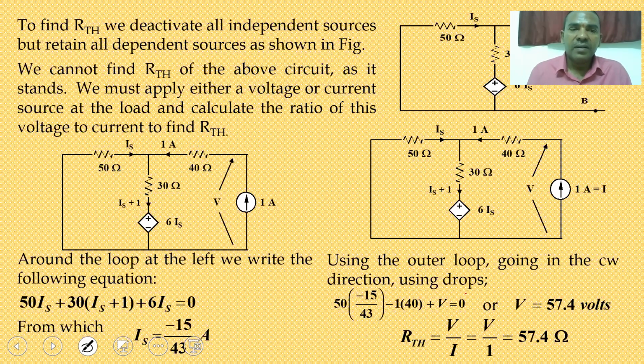So next, here I told, for independent sources, the voltage source must be short circuited, the dependent source must be activated, and the load is open circuited. So there is no current flowing through the circuit in the case of general circuits, but here a current controlled voltage source is there, so you cannot directly calculate.